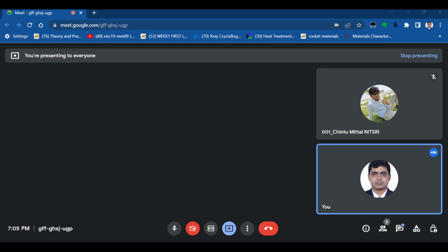So what will happen? Option A is same weight fraction of the liquid, but liquid compositions are different. From the lever rule, we need the composition of liquid and the composition of solid. This red one, everything is red here. This is the liquidus line, and this one is the solidus line. What will be the composition of liquid and the composition of solid for this composition?